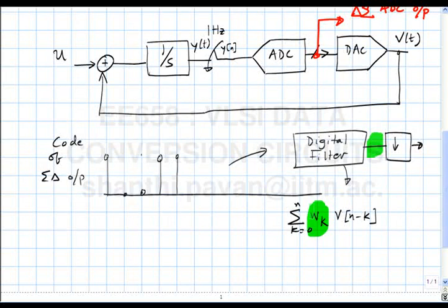And when you add all these things up, you will find that there will be round off error and so on, but you will finally truncate the output. When you add two 16-bit numbers, the number becomes 17 bits, right? So you do all the addition and then truncate off all the extra stuff. You take only the 16 most significant bits. Does this make sense? Alright. So there is a distinction here: what do you understand when you say it's a digital filter? How do you think it's implemented in hardware?